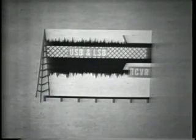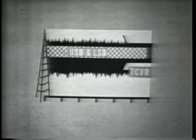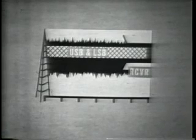And now what happens to the signal-to-noise ratio? The noise originally passed by the wider bandwidth has been reduced in the single sideband receiver. Now this means that with the same amount of received signal and only half the noise level, the signal-to-noise ratio has also been doubled.